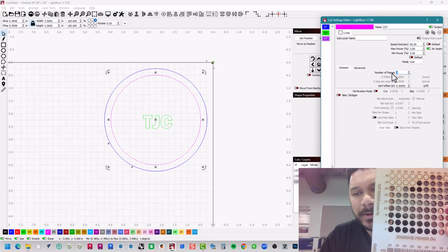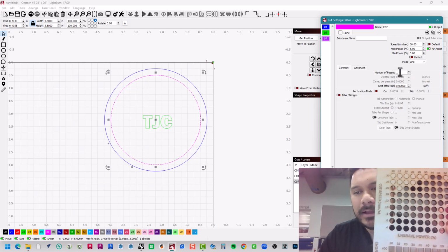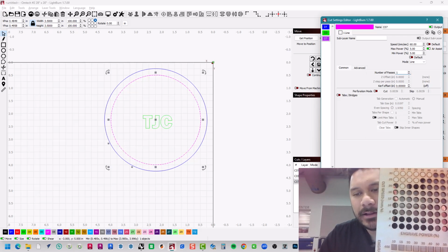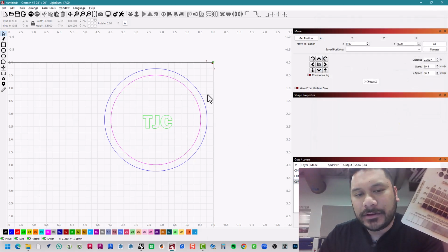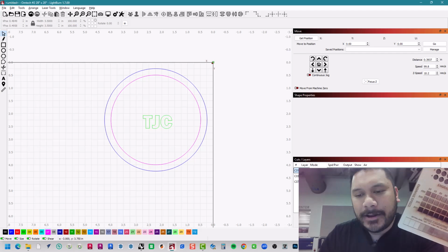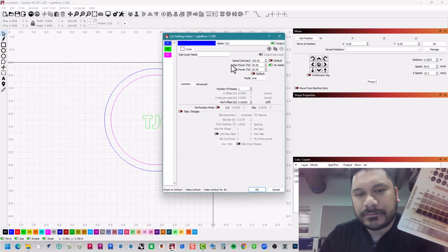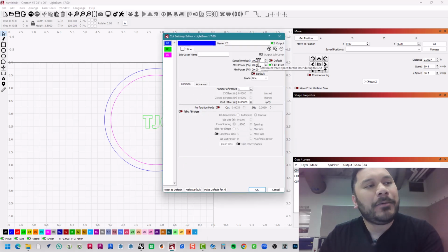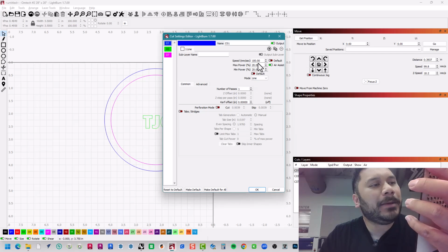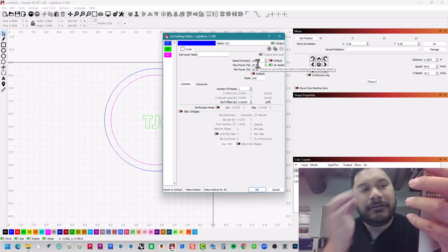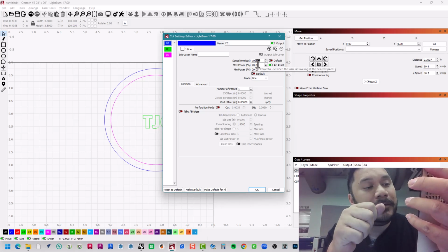So what I want to do is look at my matrix and figure out what are the best settings. Where was there less burn marks on it? What has the least amount of cleanup? Also, if possible, you want to choose something that goes relatively fast.